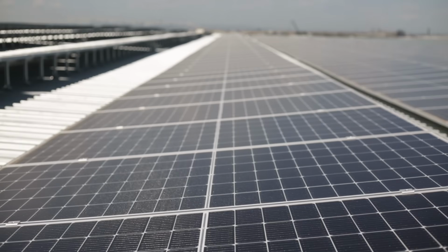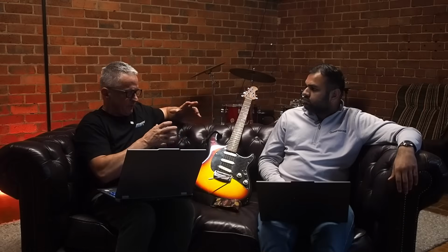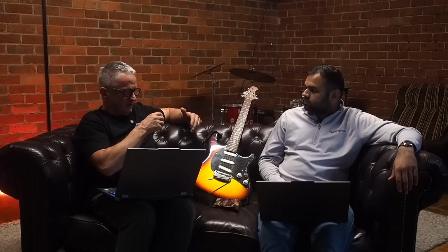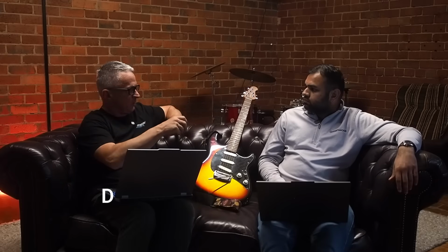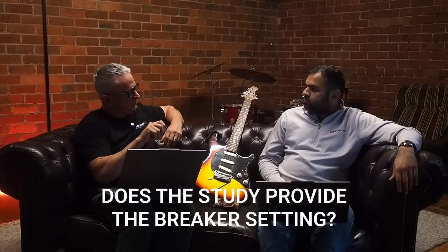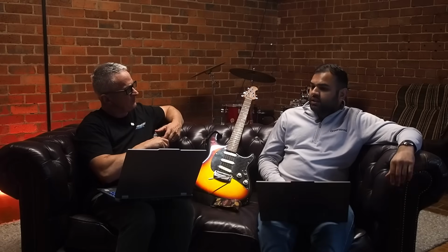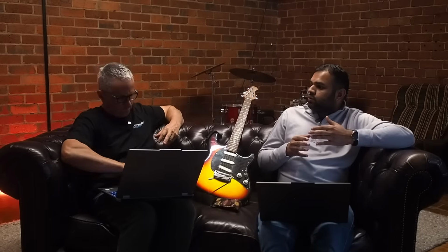So the solar becomes the sacrificial. It's the first line of defense if there's a fault current in that area. With the protection study, does it suggest within the study to the installer what settings he needs to set those breakers for? Yes. Basically, when you perform the protection coordination study, you put through all of the settings which are